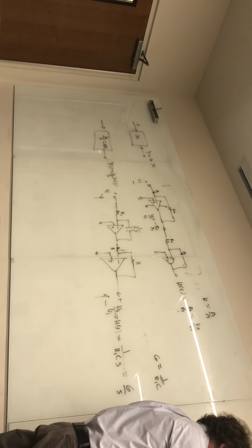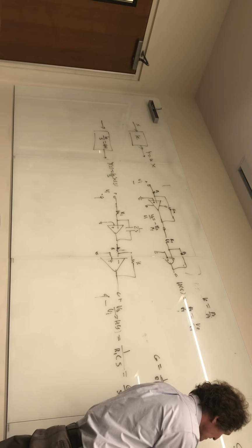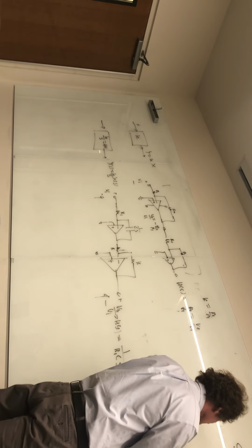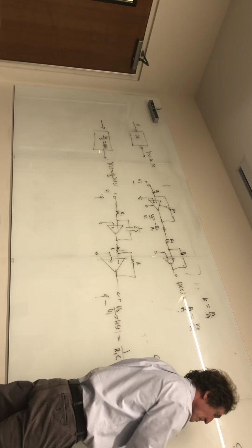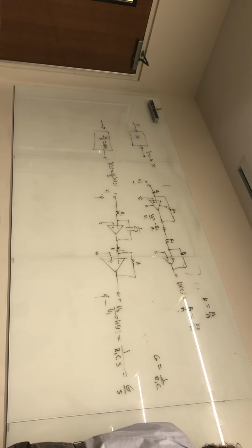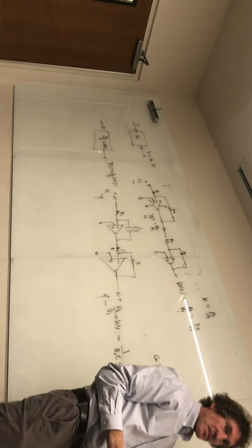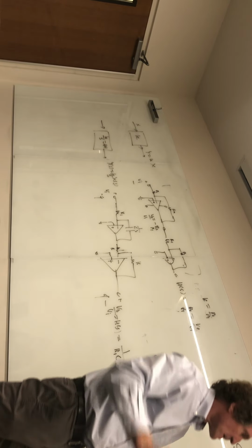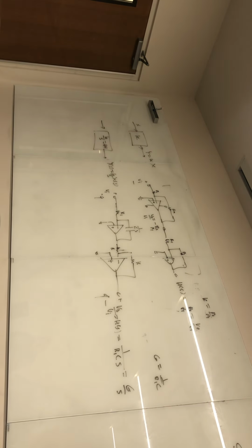Now, the real filter characteristics, if you're taking the magnitude of this, taking the log and multiplying by 20, and this is in dB, by the way, in decibels in this scale, the real value would look something like this. You would have this, and then it would not go through that point. This is called the 3 dB frequency, and I'll speak to this more later, just giving you an idea before we do the synthesis. And here the 3 dB frequency would be omega 3 dB.